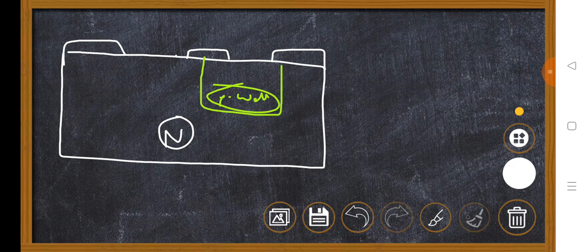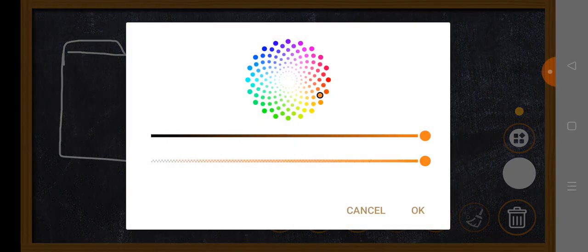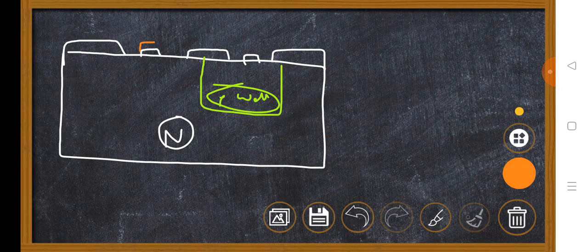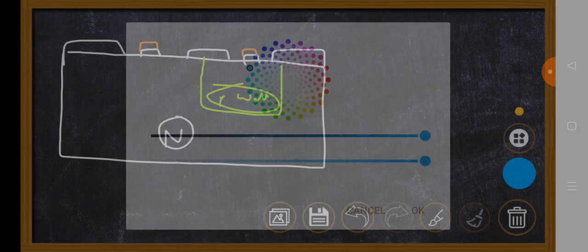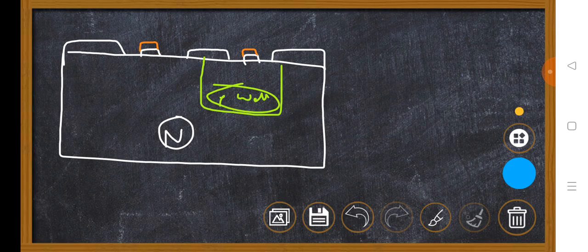Now we require a thin oxide here. This is our thin oxide. We require what? We require polysilicon. This is our polysilicon. After that we require diffusions here. Don't forget, since this is a P well, you require N plus here. This is N plus and this is N plus.